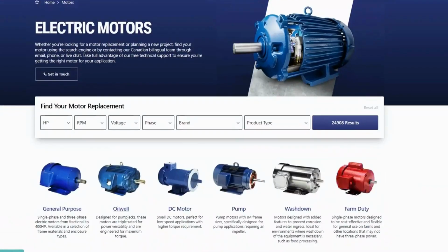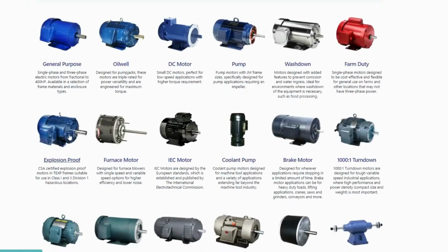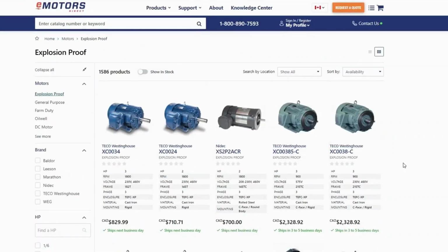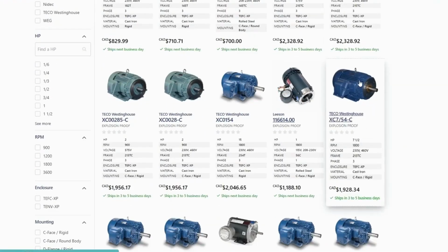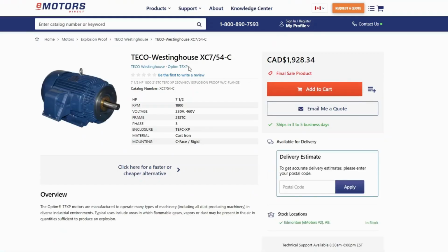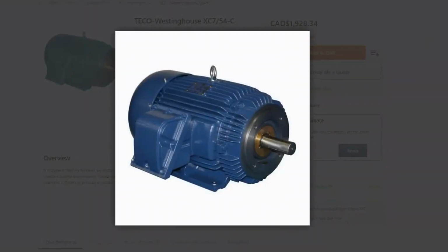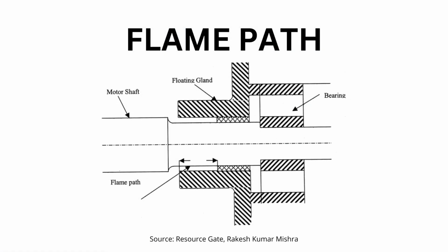Explosion-proof motors. Explosion-proof motors, which are a requirement for Class 1 Division 1 locations, must be able to contain an internal explosion of a specified hazardous material without creating an ignition source for the environment around them. This is based on the assumption that over time, the gases and vapors in the atmosphere around the motor could make their way inside, coming into contact with internal elements that could produce a spark or generate excessive heat, especially during a fault.